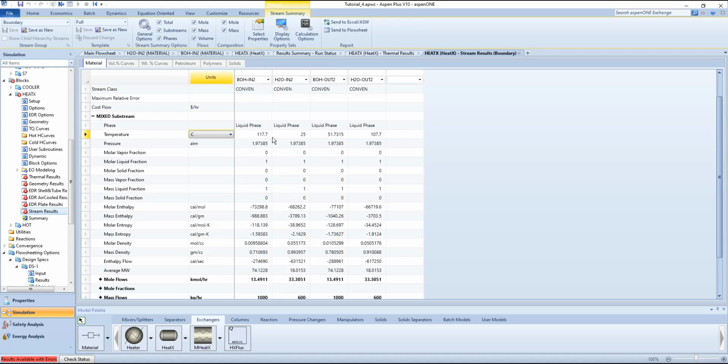So if you have a big process and you're modeling it, you're always better off using this heat X model. In some cases, you can use two heaters if you have a lot of convergence issues or you're very comfortable really looking at these scenarios and verifying all the calculations. However, if it's not the main focus, you should always use the heat X model to avoid having any sort of thermodynamic violations in your simulation.